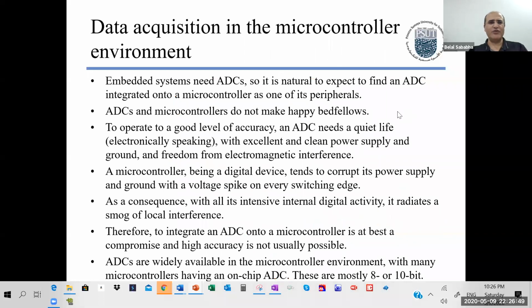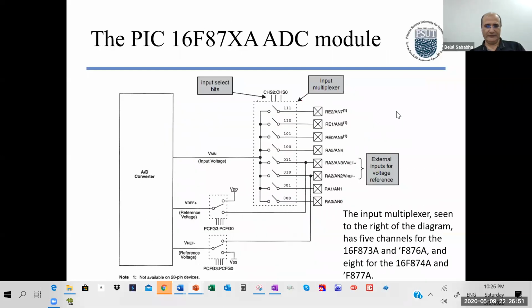So let's do an example. What do you think? But before the example, these are our signals. We said we have 8 channels, right? The 8 channels are port A0, analog 0. Analog channel 1 is connected or shared with port A1.